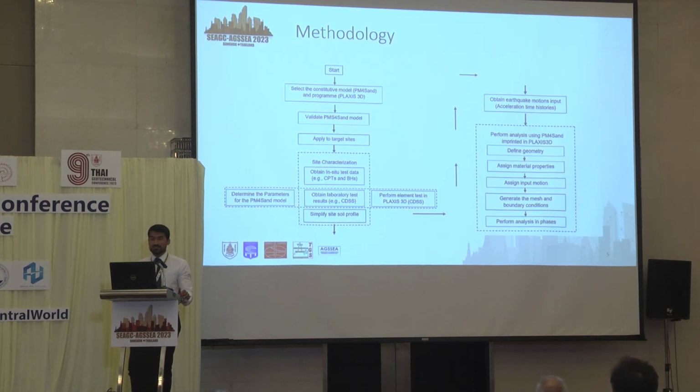Then it leads to the site characterization. As I have already told you, there is a tremendous amount of data available in the New Zealand Geotechnical Database, and some of the companies are also quite generous to offer the data they have collected in different projects for use in research at the university. So CPTs, boreholes, and all of this data was used so that we can see the soil characterization. Then other laboratory test data, if something was available, we tried to collect that. In this analysis, I haven't performed any lab tests, but I've tried to gain some from the already existing ones. Then I simplified the site profile so that I can perform a 2D analysis in the PLAXIS software.